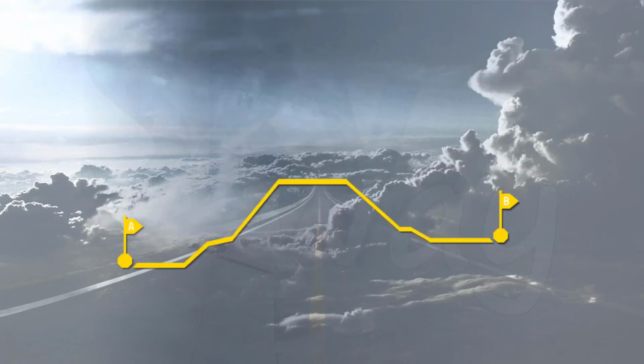Normal law is modified depending on the phase of flight. It operates in 3 modes. Ground mode operates on the ground when the aircraft is electrically and hydraulically powered. Controls are conventional.